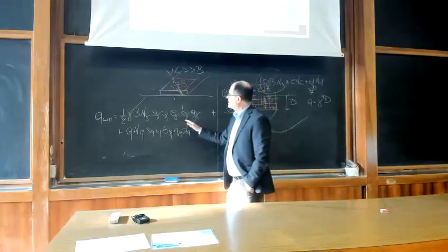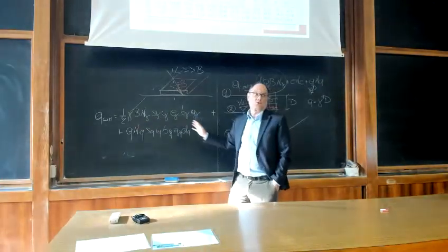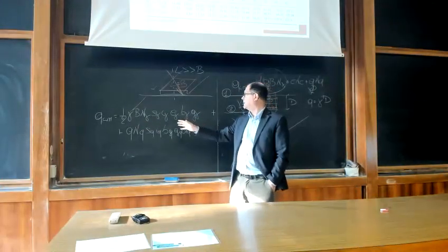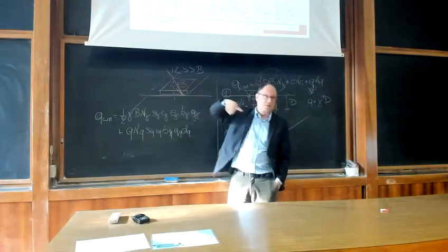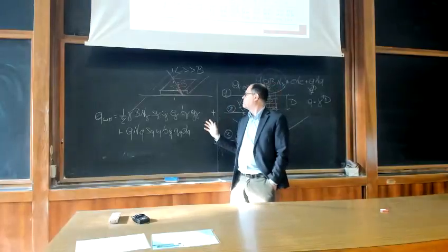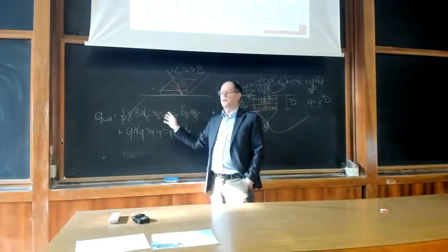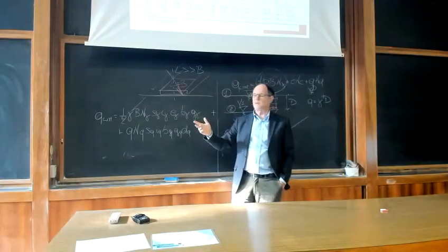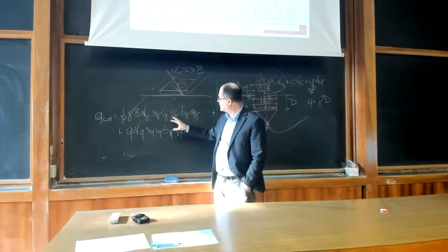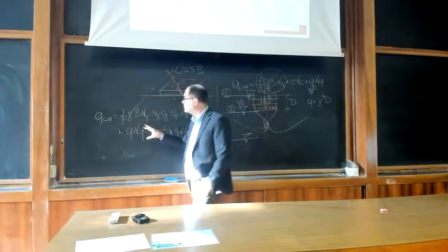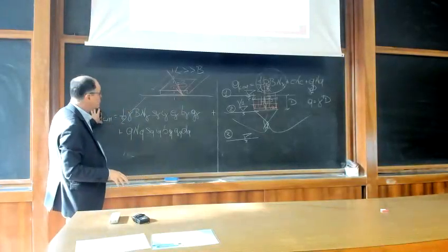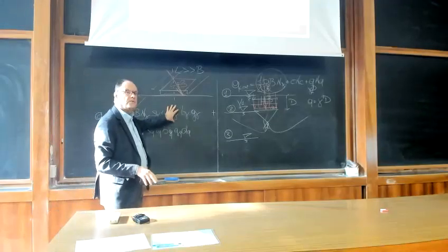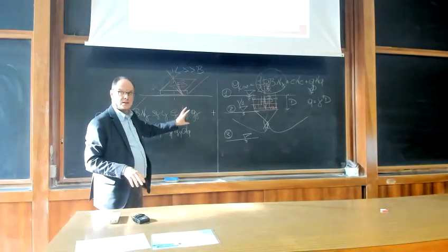Of course, most of the time you don't have all these factors, unless you are very unlucky and your foundation is inclined, in an inclined slope, the load is inclined. But you can run, once again, a sensitivity analysis and consider how much this can affect. Then you might end up with a value which is really very small, because all these correction factors are typically less than 1.